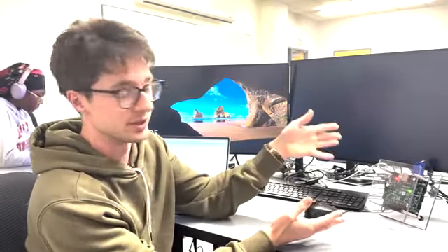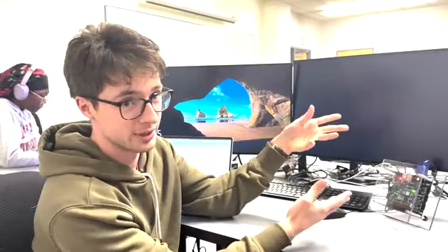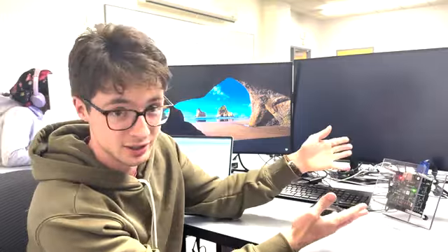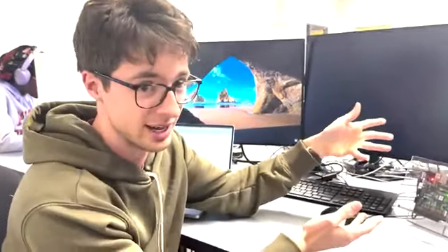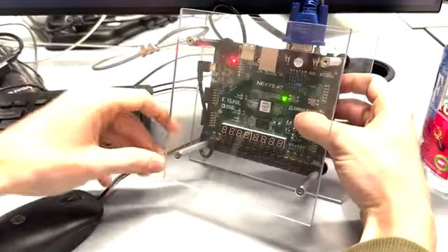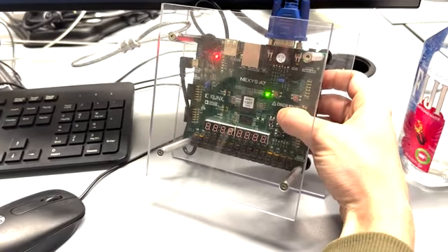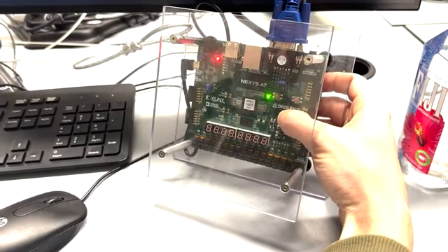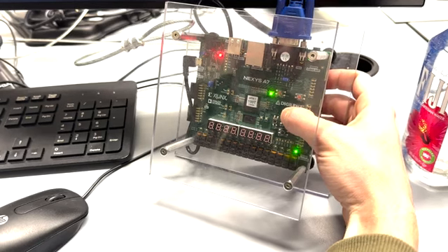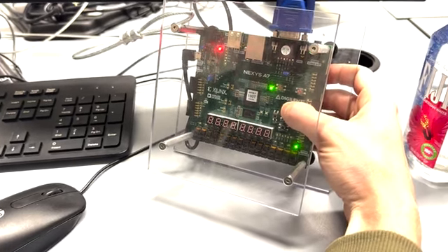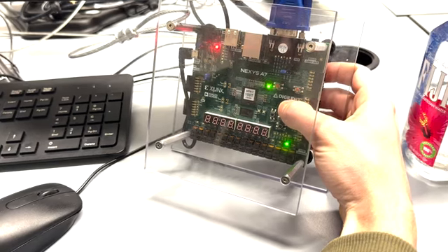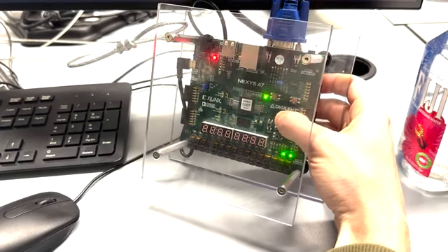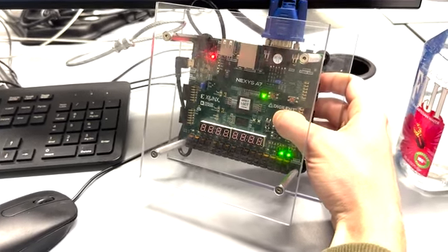And we're also showing it in a different mode where, instead of the program counter incrementing with the clock, you're able to increment it by pushing a button. So I'm going to demonstrate it counting up in the Fibonacci sequence. There are several startup requirements, like storing some variables, storing a stop condition, and starting to increment. But you'll see that as I'm slowly pushing through, you're adding the numbers, storing them, and then displaying them. And it will continue to add up the Fibonacci sequence.